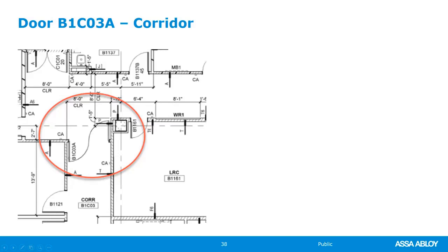Everything varies whether you're using the International Building Code or NFPA 101 means of egress. You may have multiple codes in play. Hospitals often will have 2 or 3 different codes. This particular project, we had 4 different codes that we had to fall under. And I made an Excel spreadsheet with the requirements so that if there were any differences between the code versions, the more restrictive requirement is what applies.